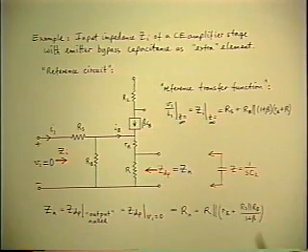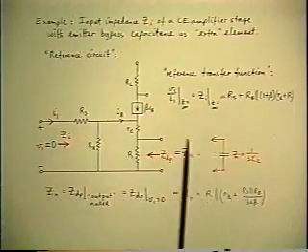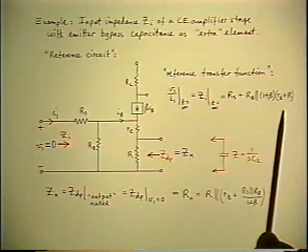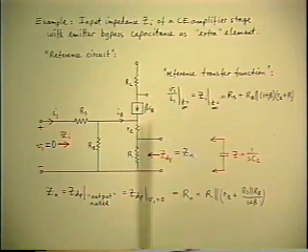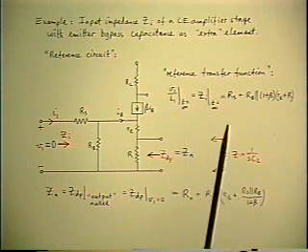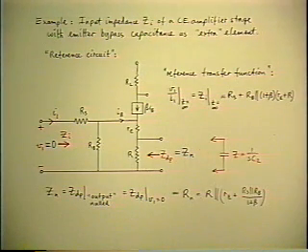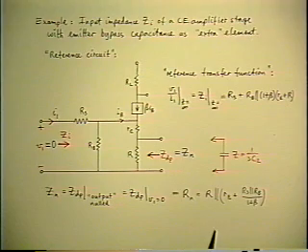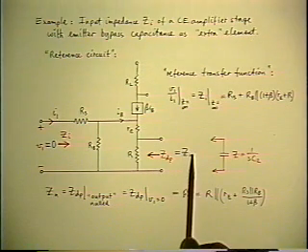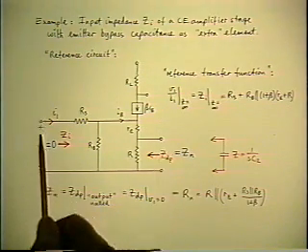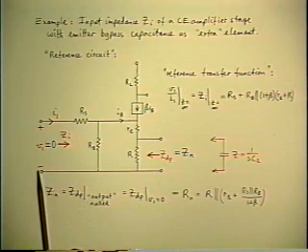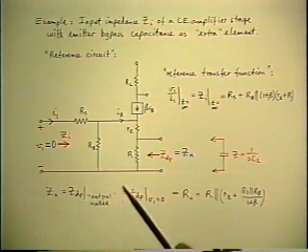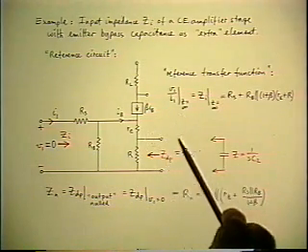Okay, the modification is that in the special case where the transfer function that you're correcting with the theorem is a self-impedance, in that case the null double injection calculation gives an answer that can equally well be calculated by simply saying that you look in from the second source with the input shorted, forgetting about the argument to do with the adjustment of the null.